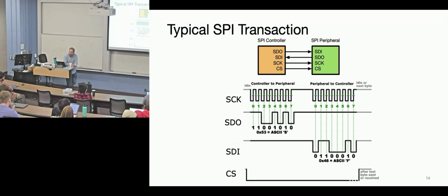In SPI, do we end up losing any bits of data during the setup phase, like when it gets stabilized, like the data in SDO? Well, the setup phase is only half a clock cycle. So here we've clocked data in, and now we're going to set up here. A transition occurred, and all the chip designers made an agreement that within this particular clock phase you can get set up within that time frame. So the negative edge falls, the chip says, okay, I'm going to change my data, and then it's instantiated on the bus, meaning it's stable, and then it's sampled on the next rising edge.